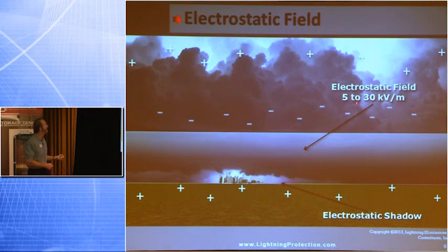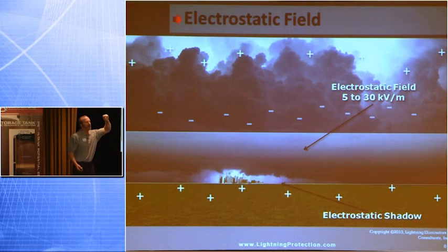Could be as high as 30,000 volts, 30 kV. So the spectrum of the electrostatic field intensity that you're going to get during an electrical storm has to be at least 5,000 volts a meter, or could be as high as 30,000 volts per meter. And that's what we're showing you in this little gray area here. This is the Earth's surface. That's the bottom of the cell. And in this area here, we have some significantly high charged air, created by the storm itself.